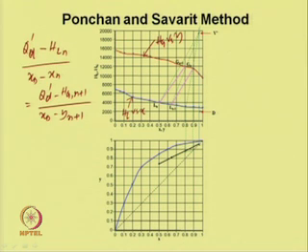A point on this diagram represents the composition and phase of a particular stream, whether liquid, vapor or mixed, and the point L_n here represents the liquid which is leaving a particular plate and entering the n plus 1 plate, and the enthalpy for this is H_L(n).